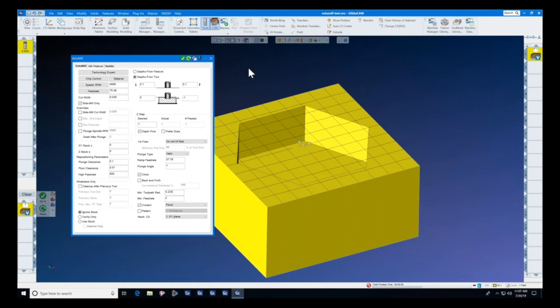You just told them you got to make sure that the radius of the tool is set, or excuse me, is set a little bit less than the radius of the tool. The setting should be... so that's the important part. I use about 25 thousandths less than the radius of the tool. There you go. And that should get rid of that alarm for you right there.